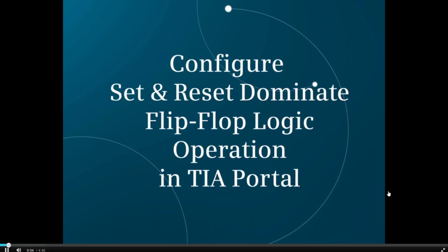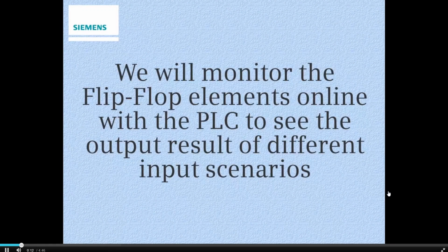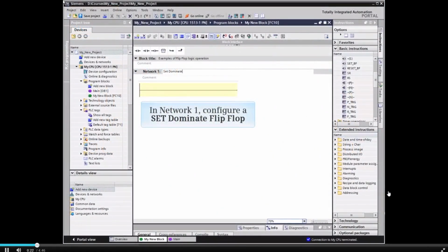How to configure a set dominant and reset dominant flip-flop logic operation in the TIA portal. We will then monitor the flip-flop elements online with the PLC to see the output result of different input scenarios. We will begin by configuring a set dominant flip-flop in Network 1 of an existing block in our TIA portal